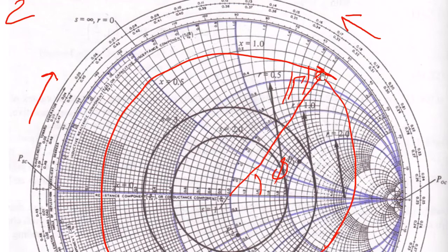So if you are at this location, you extend this part up to here, and you can find this angle phi is equal to something. It is 40, 50, so it is around 55 something degree. So you can just measure this angle. You extend the slice, you join these 2 points, and you extend here and cut here.